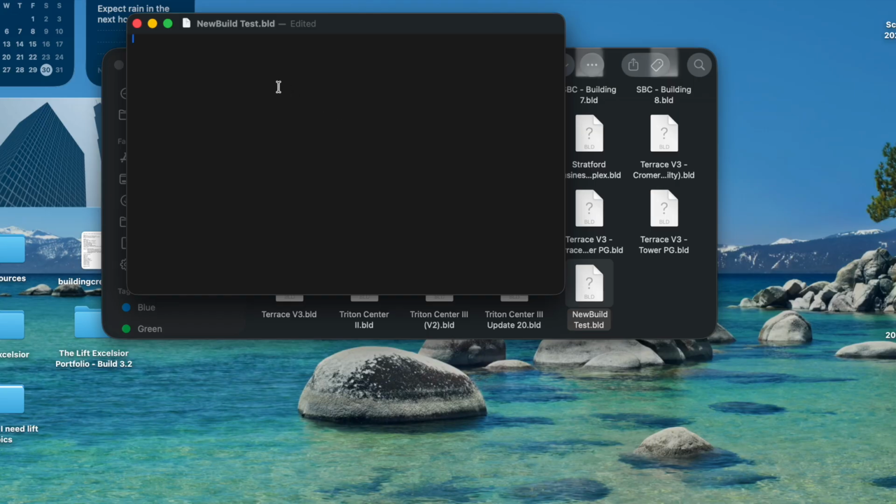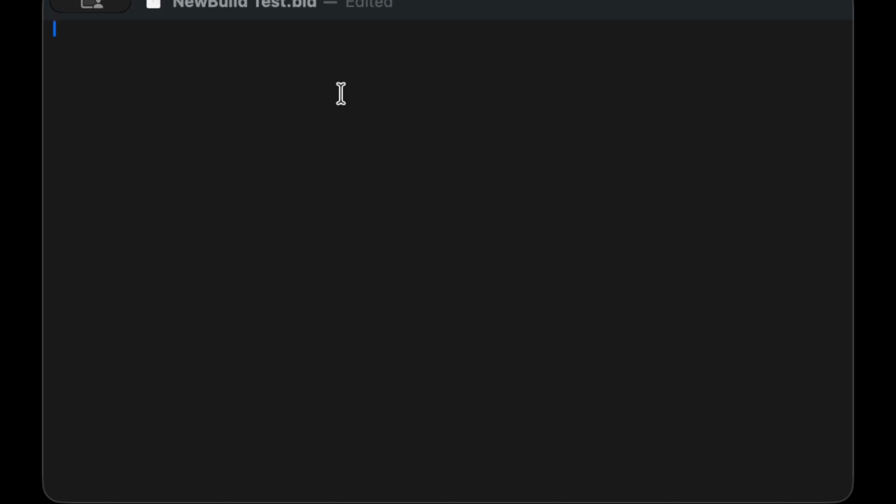Start coding our building. And here is our BLD file. The first thing we have to do is we need to include the NewBuild script. Do this by typing just a single line. So we do an angled open bracket, include NewBuild/script.txt, closed angle bracket. This one line sets all the global parameters, includes all the textures, defines the floors, and does all the preliminary work. So as soon as after doing this, you can immediately start making your building.